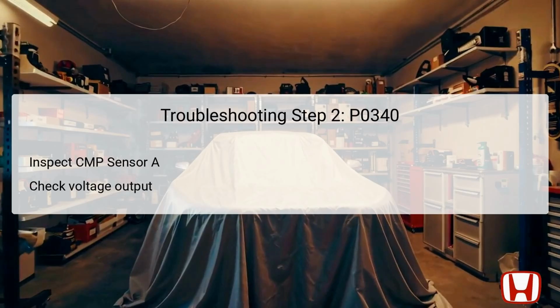Normal operation should yield approximately 5 volts. If the sensor's output is normal, the sensor is likely functional, and the problem may lie elsewhere. However, if the output deviates from the expected voltage, it suggests a problem within the sensor itself. Conducting this inspection provides actionable insights on the state of the sensor.